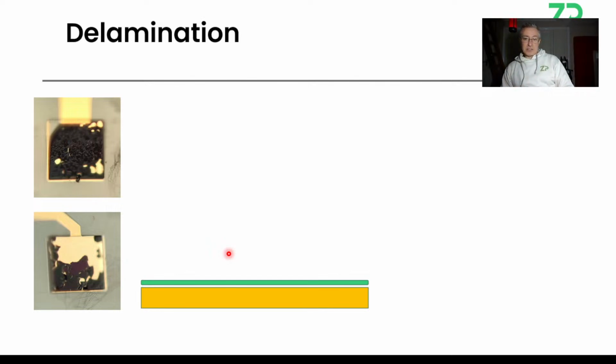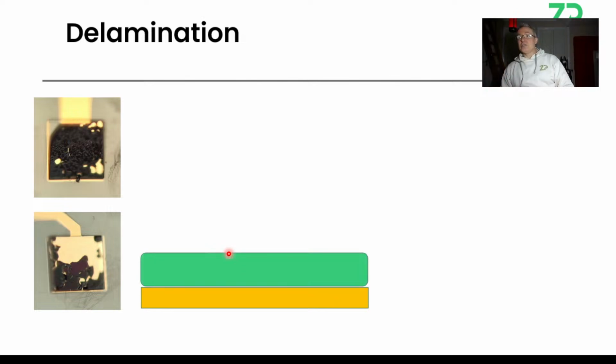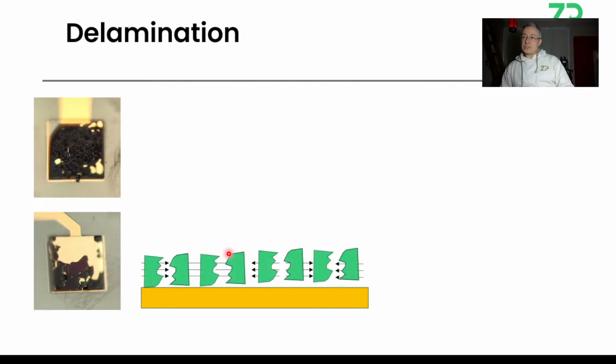What would help is if it's a thin layer, but these are quite dark layers when you look at that. So when they've got a thicker layer, and it dries out, you get these internal shrinkages, and the internal shrinkages can lead to this kind of breakage. So it's very thick. If it was thinner, it would probably adhere better.